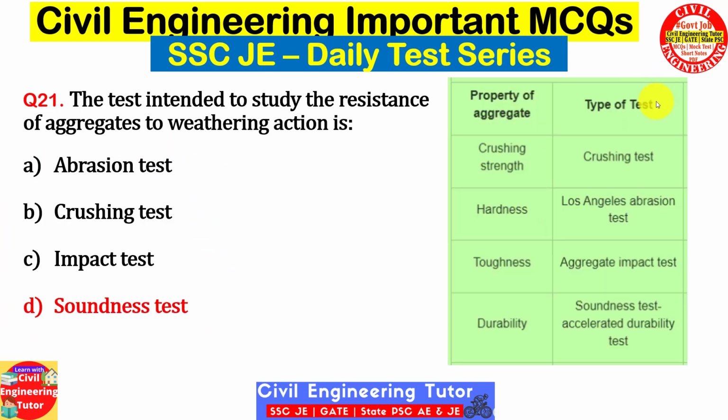And here is some reference for other tests also. Crushing test is used to measure crushing strength. Los Angeles abrasion test is for hardness property. Aggregate impact test is used to measure toughness. And soundness test is used to measure durability of aggregates. So just remember all these points. It may be asked in any way, like which test is used to measure crushing strength, and you have these options, so you need to select one of these. Just remember this reference.